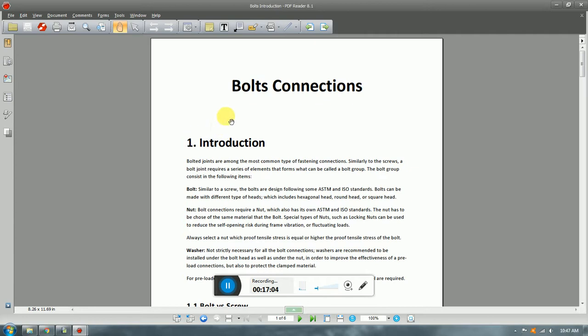It's important to say, any fastener has up to 3 standards, okay? You should know them and you should use them, okay? The first of the standards is going to be the dimensional standard. That is going to tell you exactly what the standards are, and it's going to tell you exactly the tolerances, exactly the pitch, exactly how many fillets you get, the design of the head, everything, okay?